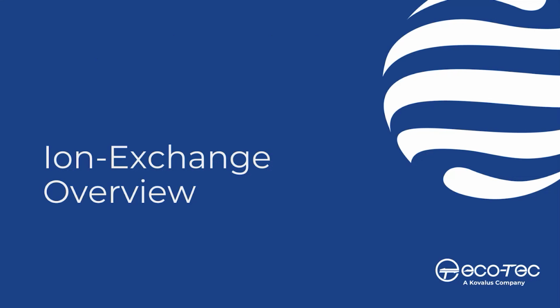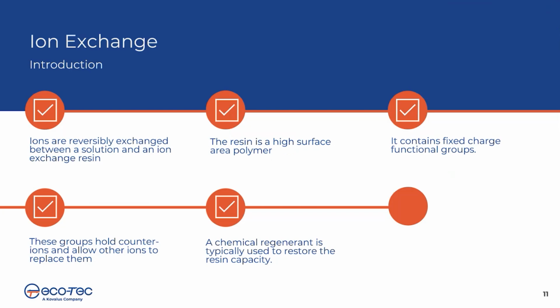Okay, before going into the core mechanism, I'll do a quick ion exchange refresher so we are aligned on the fundamentals. Let me frame ion exchange in plain terms. You have a liquid stream and the resin, and ions are reversibly swapped between them. The resin is a high surface area polymer with fixed charge functional groups, and those sites selectively hold certain ions from the solution, while other ions replace them to maintain the charge balance. Over time, the resin capacity gets used, so you typically apply a chemical regenerant to restore the resin and repeat the cycle.